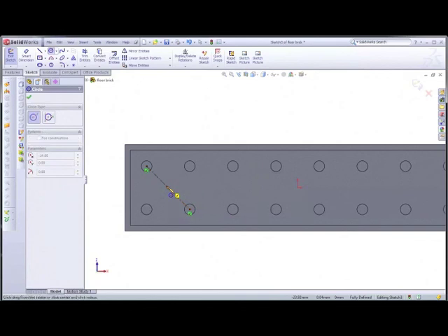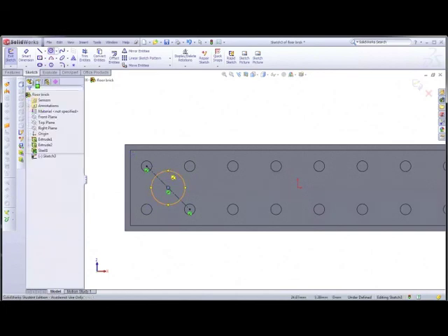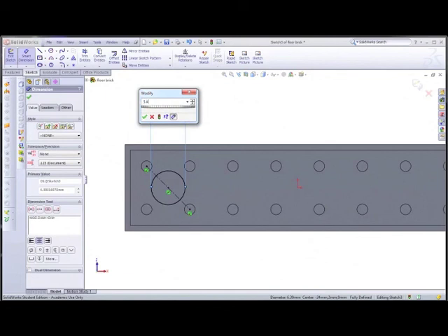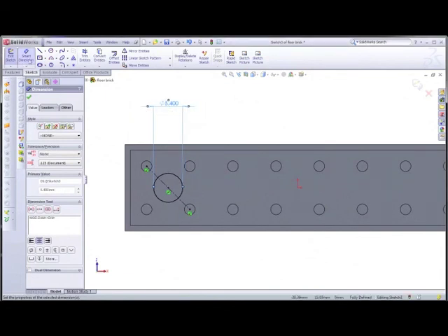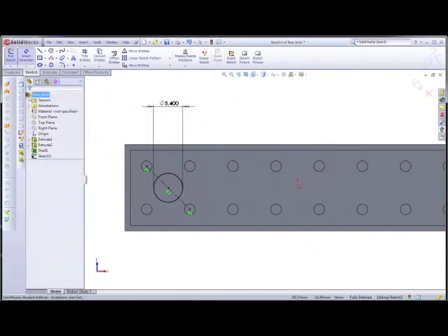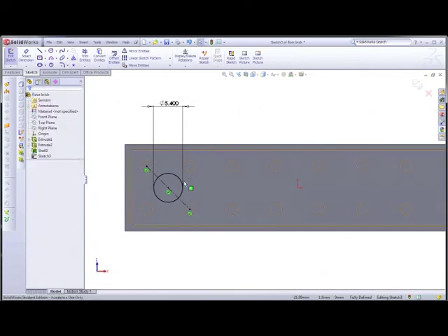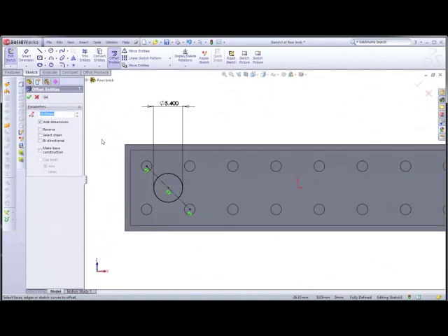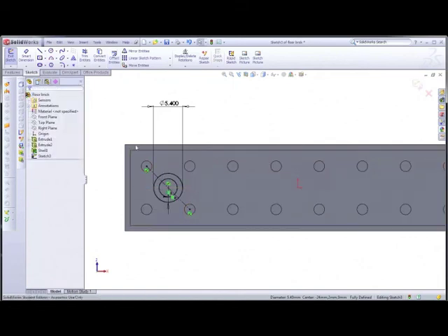Okay, now we click on the centre here, and we will put that there, like so. Smart dimension this to 5.4. Exit that. Green tick that. Now we can offset by 1 millimeter. If we use the offset tool, remember before we had to cut back down, but we can avoid doing that by just literally offsetting this by 1 millimeter, green tick, and select there, and select reverse direction because we want it to go inwards, green tick that,